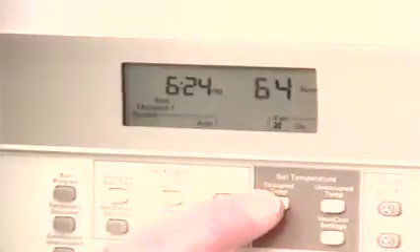Okay, so each system has its own thermostatic control then? Yes. Okay, will you show me where the thermostat's at and we'll see what we can do for you? Sure, that'll be great. As the customer said, the room temperature is only 64, but the thermostat is set at 74. The airflow at the supply register is adequate, but the temperature is only lukewarm.